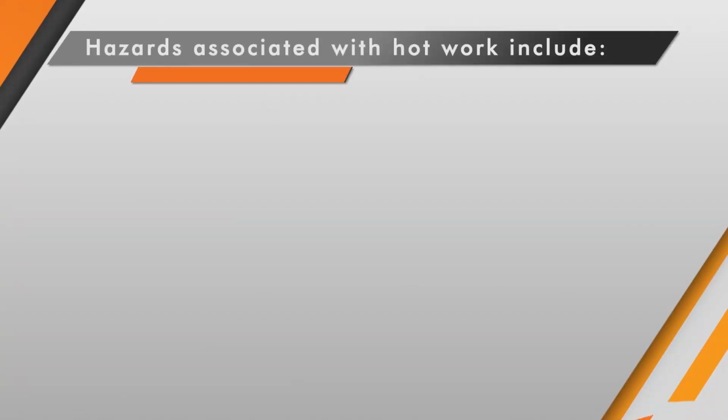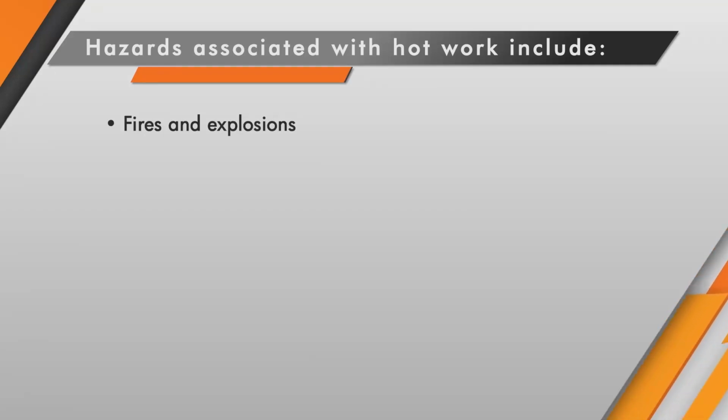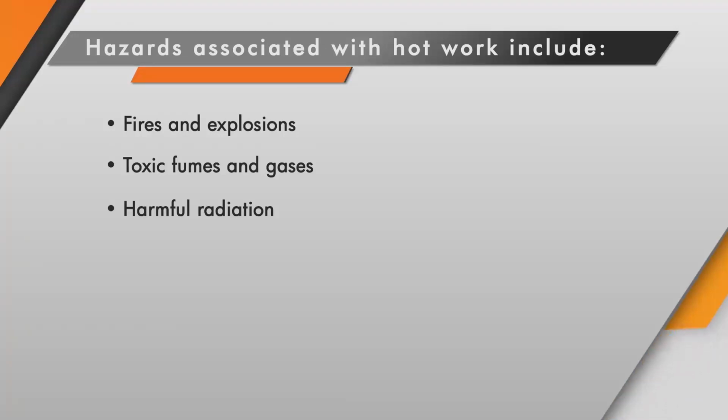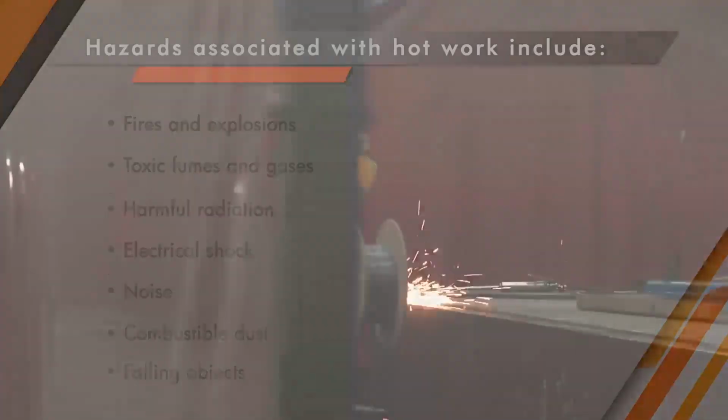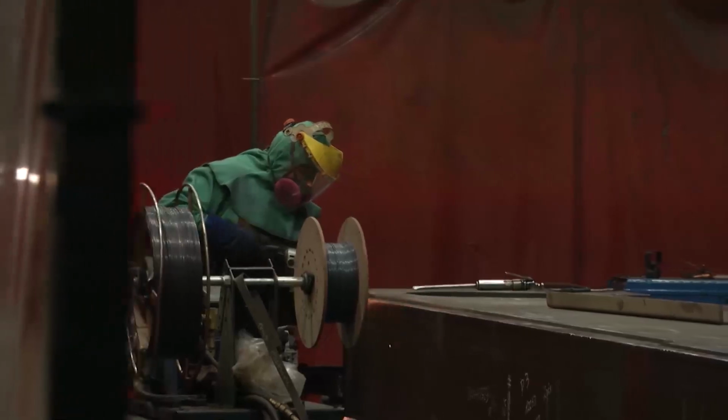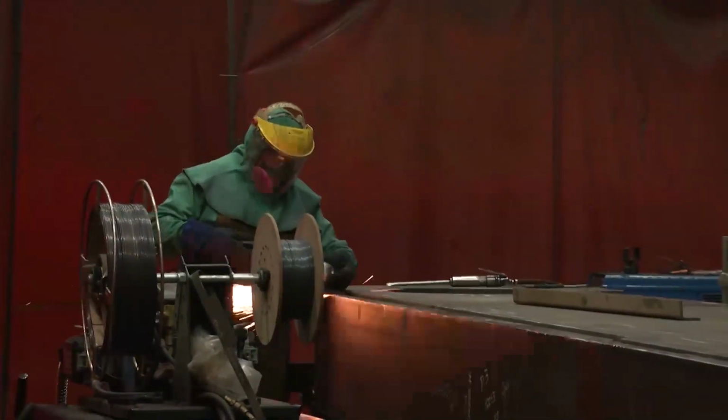Any work that involves burning, welding, using fire or spark-producing tools, or that produces a source of ignition is referred to as hot work. Because of the nature of the work being performed, there are a number of potential hazards associated with hot work, including fires and explosions, toxic fumes and gases, harmful radiation, electrical shock, noise, combustible dust, and falling objects.